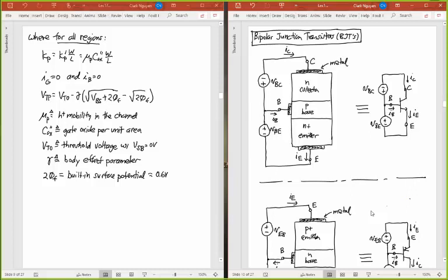For a lot of discrete circuits though, a lot of it is bipolar. A lot of this has to do with bipolar circuits being more resilient to electrostatic discharge. That's when, say, you walk around, especially in wintertime, dragging your feet on the rug, you develop a charge, and then you touch a transistor. You touch that NMOS transistor, it's dead, because there'll be too much current flowing through it. You touch the bipolar transistor, chances are it'll survive. So for off-chip applications, bipolar transistors just work better.